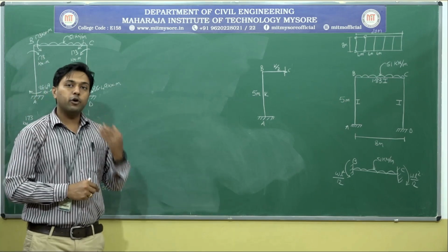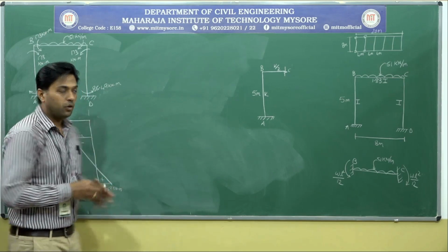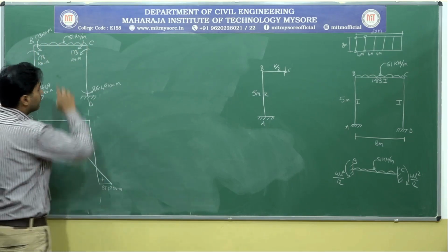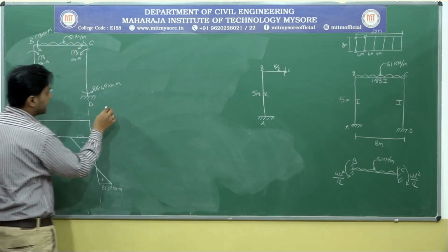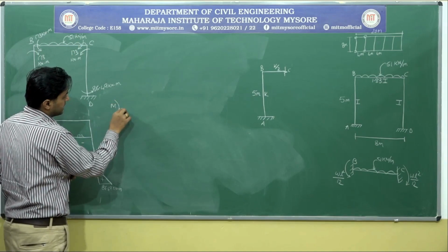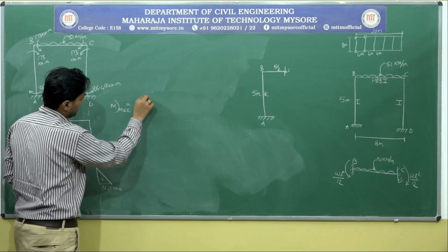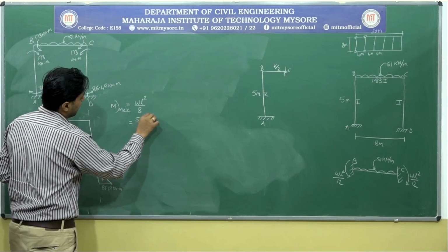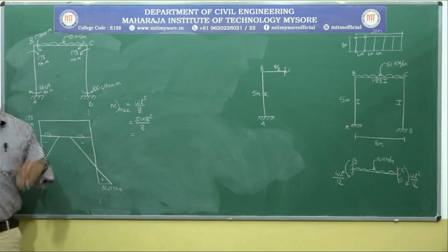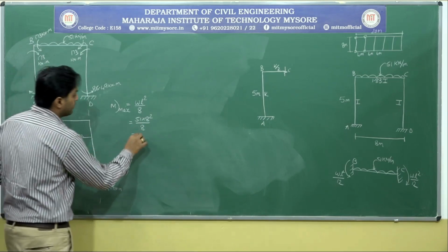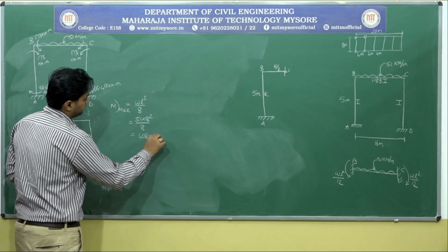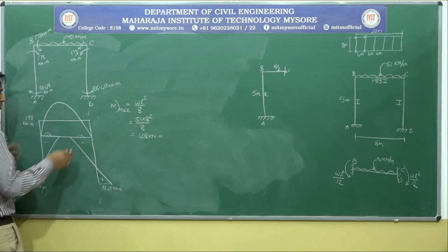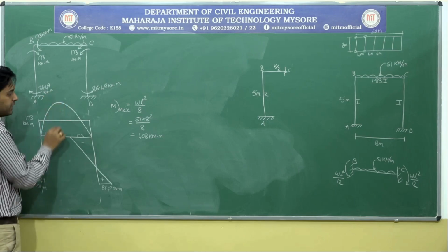But if I want to go with the design of the beam, I will be concentrating on this. So there is a new deal. Let me calculate the maximum bending moment. Whenever a beam carries a UDL, what is the maximum bending moment? The formula is WL square by 8. So W is 51 into 8 square by 8. The total value that we are getting is 408 kilonewton meter. I think you people know that it comes like this. Yes or no?